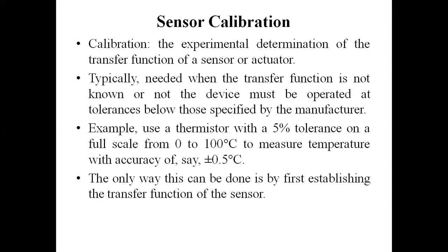It should be further noted that an instrument is calibrated at one place and is good to use at some other place. Care should be taken that the instrument is used at a place where the environment has the same conditions as the places where the instrument was calibrated, to ensure that the instrument gives correct readings.